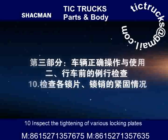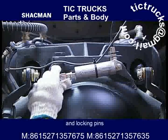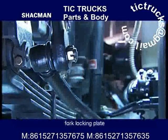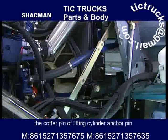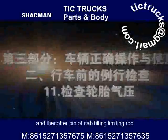10. Inspect the tightening of various locking plates and locking pins. Inspect locking conditions of the differential lock cylinder fork locking plate, the cotter pin of drag link, the cotter pin of lifting cylinder anchor pin, and the cotter pin of cable tightening limiting rod.